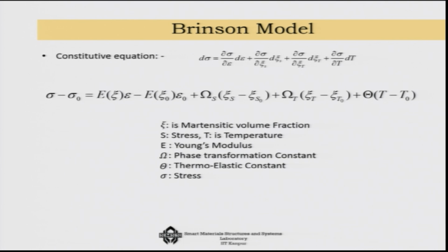If you look at the Brinson model, you will see that the stress strain relationship here is given in a differential form. Okay. Now, as you can see, the first part is the Hookean part, that is your common everyday stress strain relationship. Then you also have another part which is related to the pre stresses that happen in the system, which you can include in this.